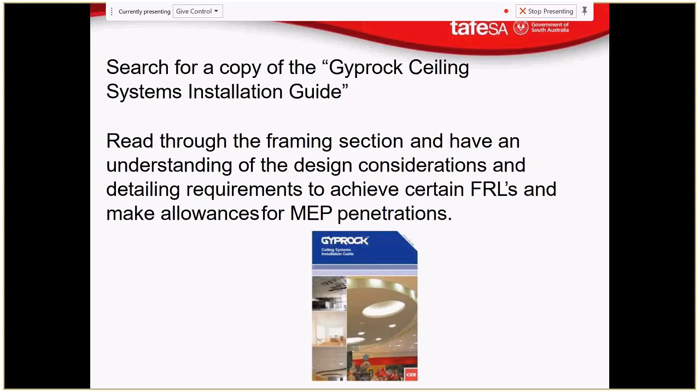So if you have an aluminium jointing piece in there that allows the plasterboard to move a little bit, but doesn't show up any cracking, then it meets its performance, what's demanded of it. Okay.